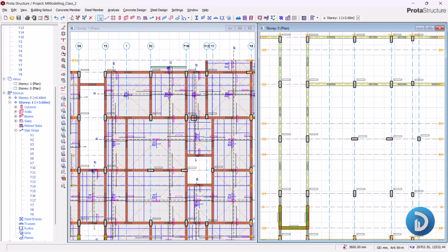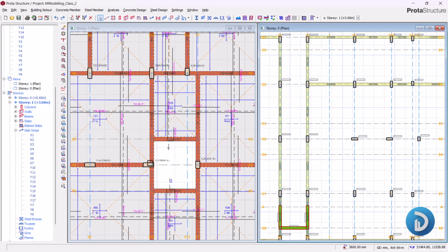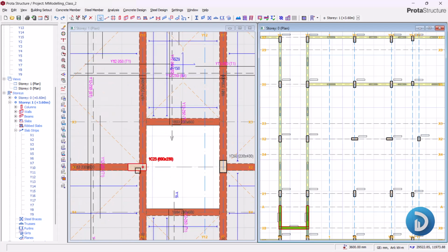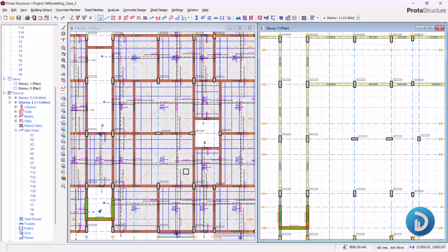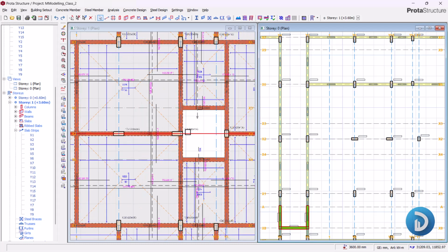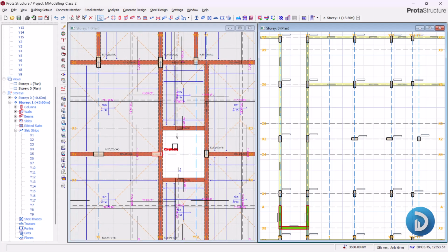All right, but in order to create a very rigid frame at the foundation level, we'll have to connect this beam from this point to this point, so we can have this as one panel and we'll have this other one as another panel. Why will this serve as another panel? This is just to enhance the rigidity of this level, so we don't have beam resting on beam. We can have beam connected directly from the columns.